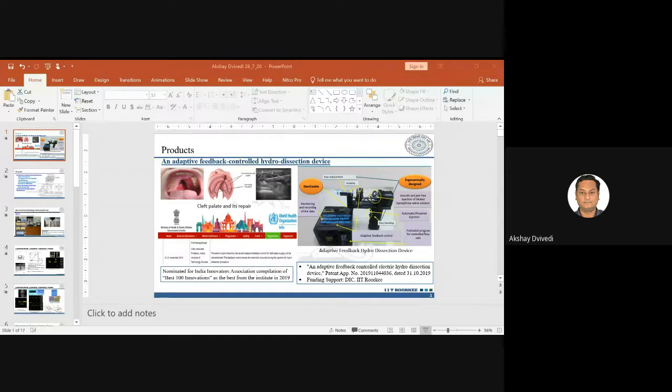But as you go beyond this particular depth, this means when you are penetrating inside the work material after 300 micrometer, you reach a particular zone wherein the hydrodynamic regime comes into picture. Now, these are two technical things for some of you, but if I have to give you a very simple understanding, up to 300 micrometer depth, discharges are acting, which is basically creating consistent discharges.